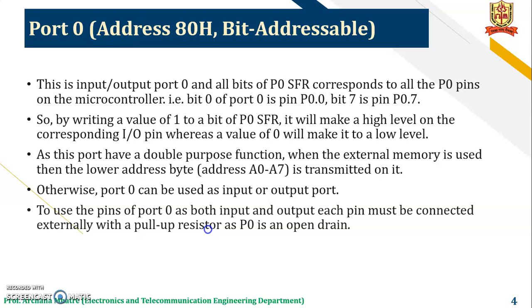That is, bit 0 of port 0 is pin P0.0 and bit 7 is pin P0.7. So by writing the value of 1 to a bit of port 0 SFR, it will make a high level on the corresponding input-output pin, whereas a value of 0 will make it a low level.